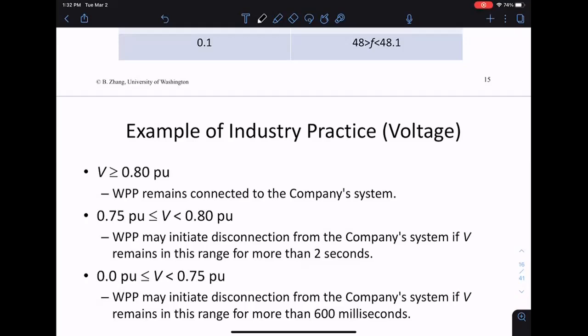For type 4, you basically have a generator, then an AC to AC converter. So for a type 4, no, you're not very sensitive to frequency. You can change your frequency at the output of your converter to match the system. Whatever the system frequency is, you're not particularly sensitive to it.